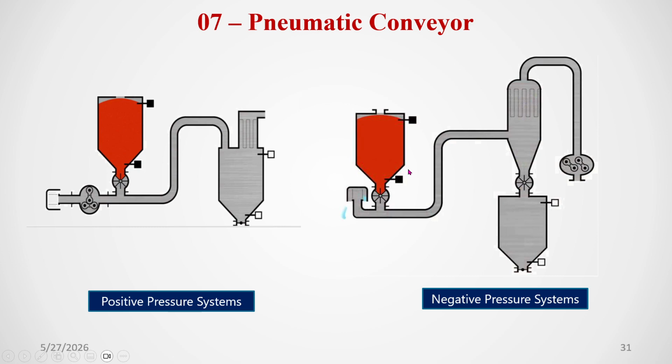Here it is negative. You see, here the blowers are provided at the end. From here, air is going to be sucked, to the chimney. From here the material will be there. Due to negative pressure, when you run this, negative pressure will be generated, so material will fall down through this feeder gradually, and air will be sucked from this, and it will go through this pipe to